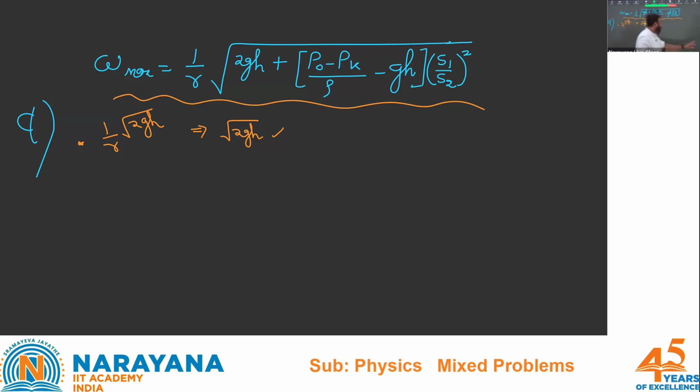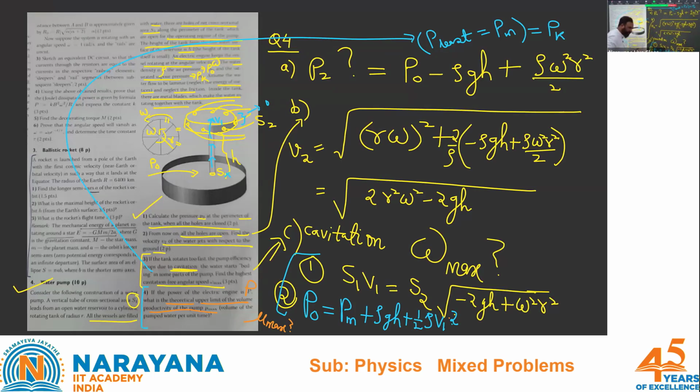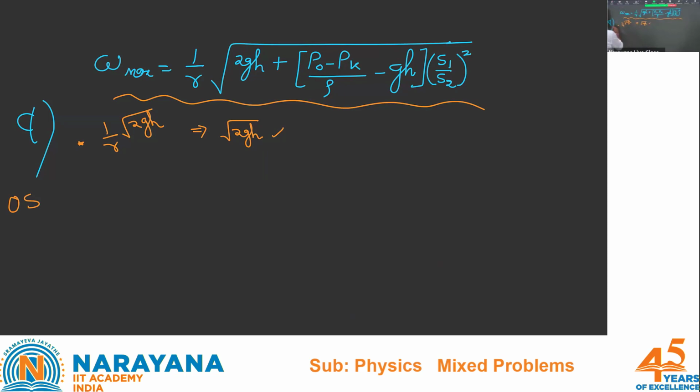Under any situation, you have to understand that this language will have a subtle implication. What I am trying to do right now is find out the least energy that I have to spend. Two things are happening categorically. One thing is I'm lifting liquid by a height of h, so some energy is definitely to be utilized under an optimal situation. Two things come to my mind. One is, if I write mass per unit time as mu, I'm writing mu as my m dot, so mu gh, that is one consumption. You are lifting it by a height of h.